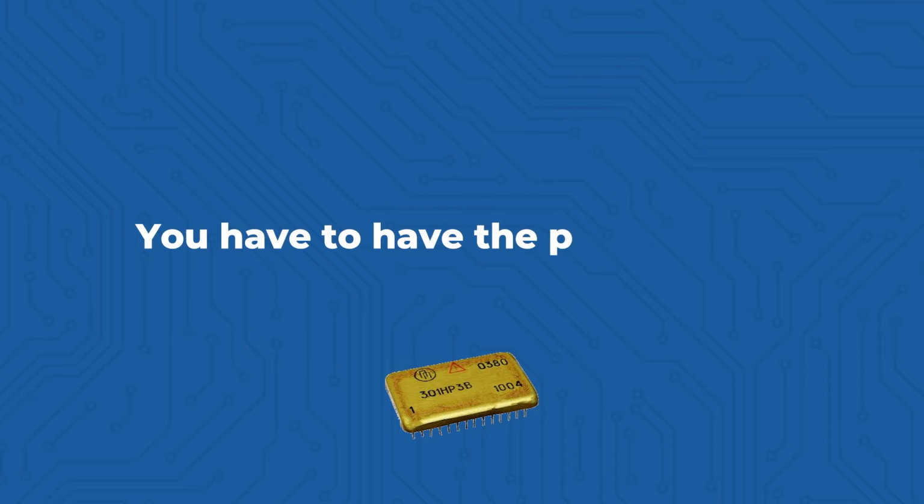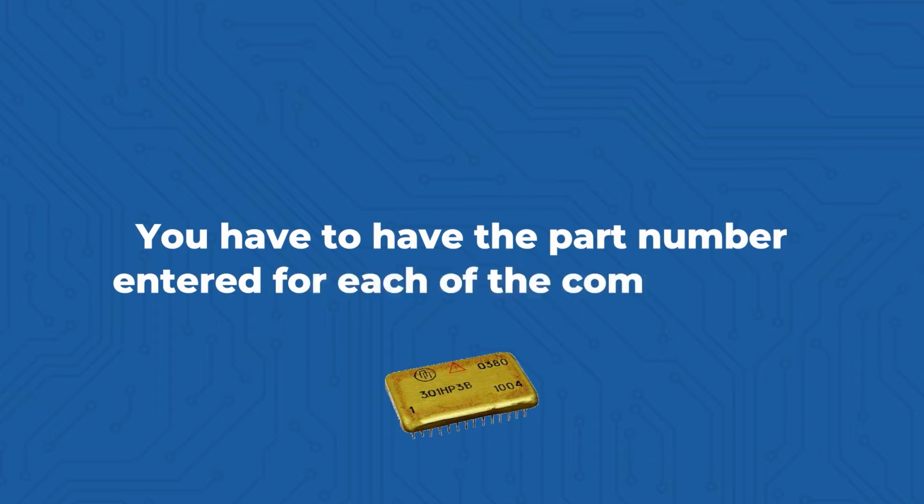For instance, you have to have the part number entered for each of the components. That's not required when you're creating the schematic, but it is something that you'll want to do before generating the bill of materials, so that you can just regenerate the bill of materials as needed. You want to make sure you include all the part numbers and component values in your schematic.